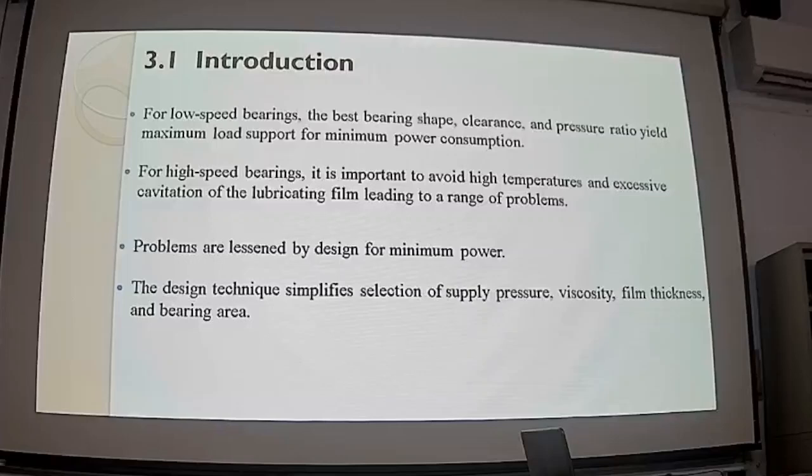It is very difficult to manufacture. But you cannot choose the film thickness too big, then you lack stiffness. It differs from factory to factory. Some assembly workers say a given gap is very hard to fit, taking over ten minutes, and some are simply not possible. So you can get feedback on the film thickness from your assembly worker, from the manufacturing process of the assembly line.